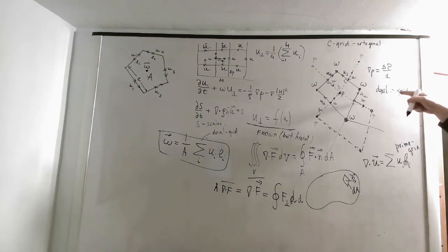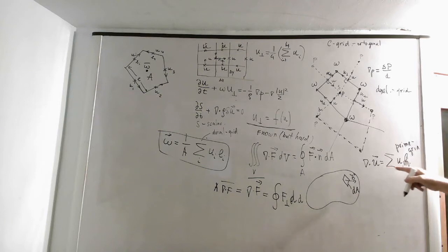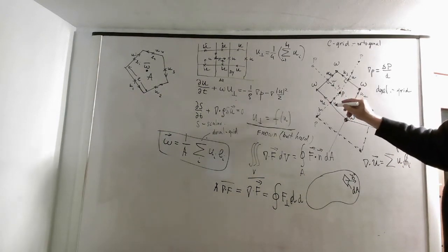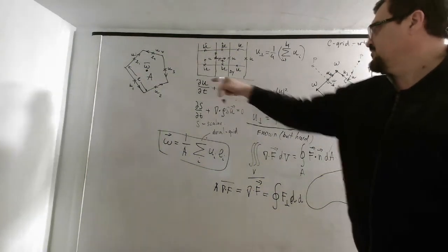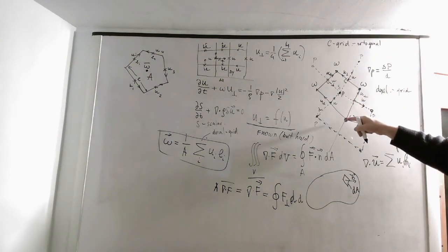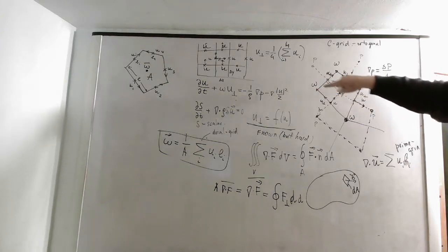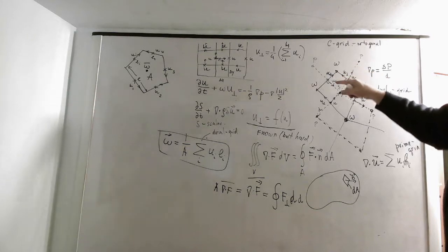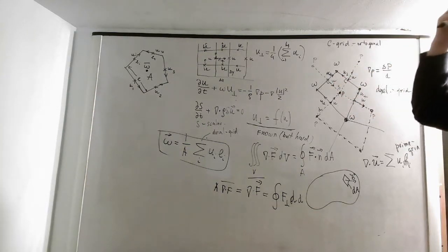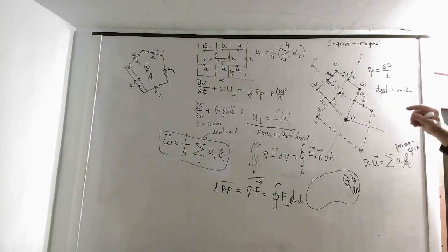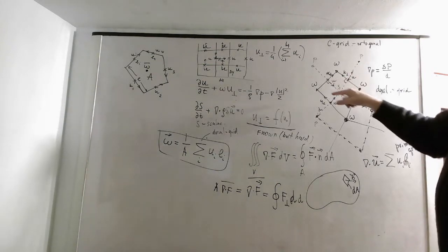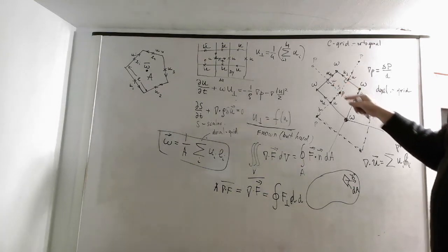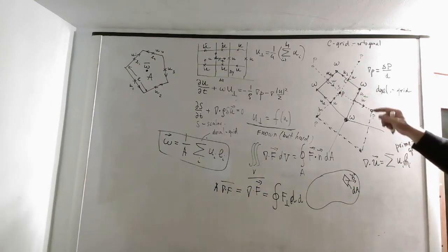So vorticity was on the dual grid, and here it is on the prime grid. But it's the same. You just take a velocity perpendicular. So this is what your prognostic variable is, and multiply by the distance between these omega points, between corners, and then add this and add this, and of course looking at the direction. That's important. It should be in the same direction. So there is some sign rule involved in how you take this contour integral depending on a direction.